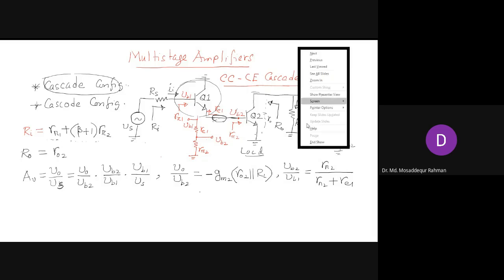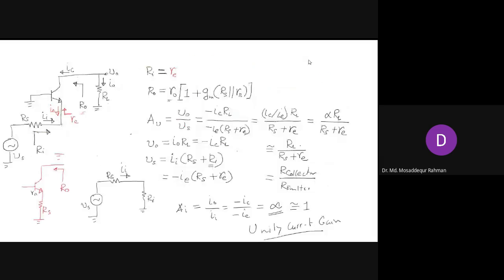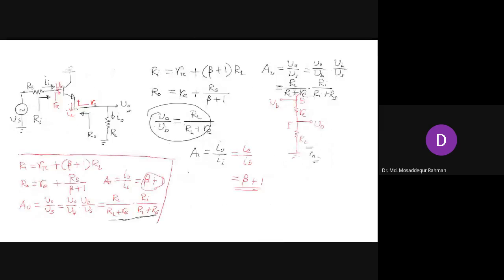So that is what we have in that circuit we have shown you. See that RL, the load resistance for Q1, and that is the input resistance for whatever is connected here. This load is whatever is connected at the emitter of Q1. That is like the load resistance. It can be a resistance, it can be other circuits, you don't know that. So we can replace it by RL and it will be the same input resistance of the circuit.